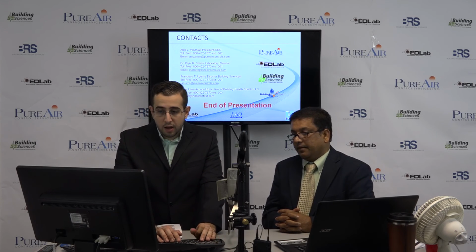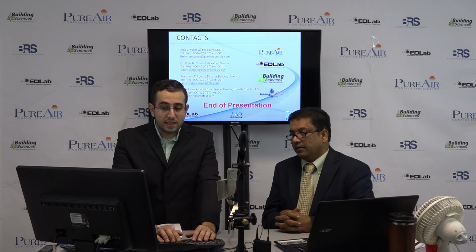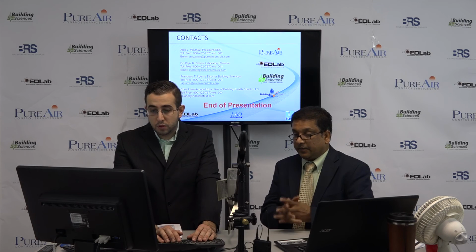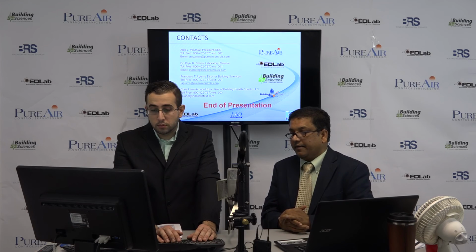Okay. And it looks like a final question that we have is about respirator use. Is respirator use recommended when collecting samples from cooling towers? Yes, certainly, especially when the condition is known or the bacteria is suspected, then it is always a good idea to have a respirator, because as I was explaining, this bacteria can also be transmitted in terms of aerosol droplets.